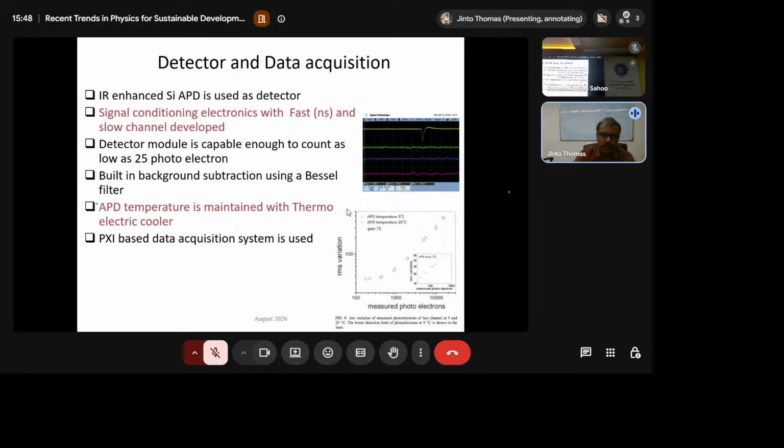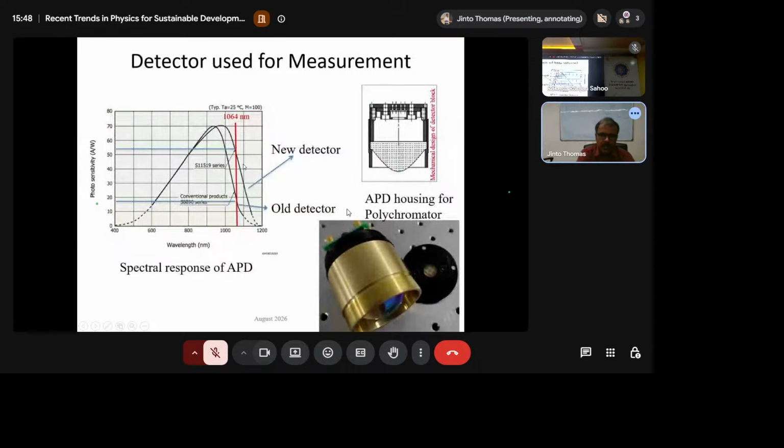It is not a counter, but everything is happening within 10 to 20 nanoseconds, getting such a small signal and subtracting it from the plasma background also. The detectors used are avalanche photodiodes. We have our own lens and electronic system, which automatically make sure that the photons collected and transmitted through the filter reach and precisely fall within this 2.5 mm, because this setup is made such that the light is focused automatically onto the APD kept here.